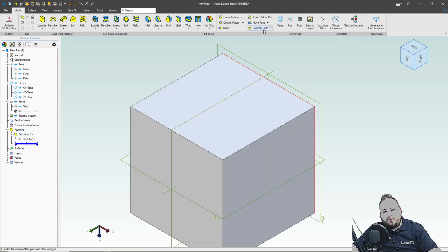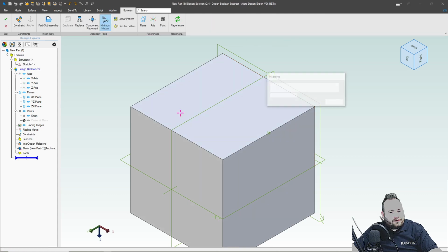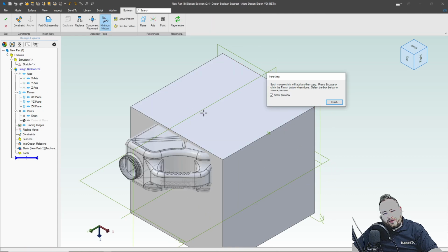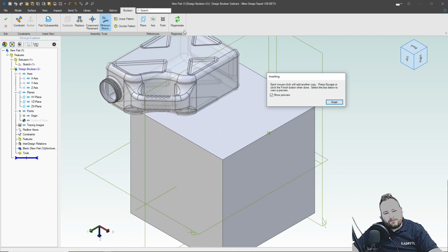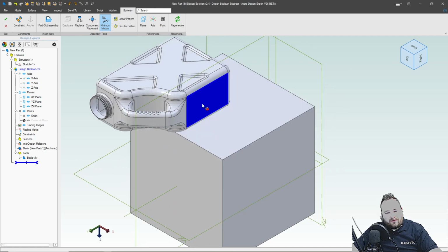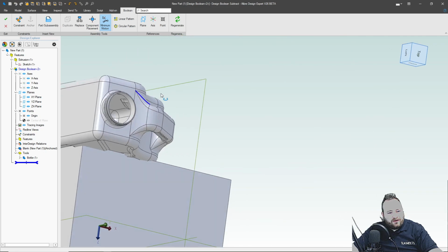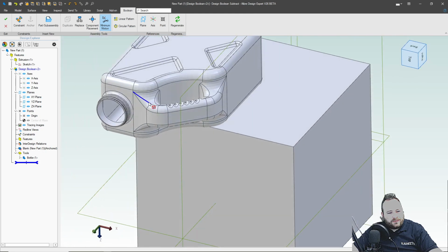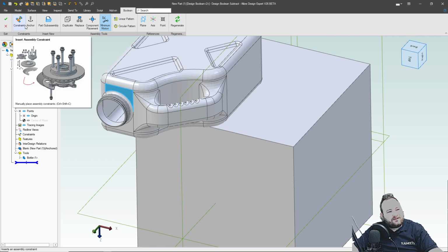We're going to say Boolean subtract, and I'm inserting the bottle that I've just made, or at least a bottle that will work, right? So we've got our hollow bottle. Let's say that we fill the fluid up to the level of this face. Obviously this is an external face, but we'll say that the internal fluid is at the level of this external face.